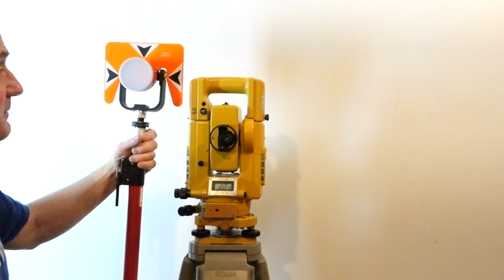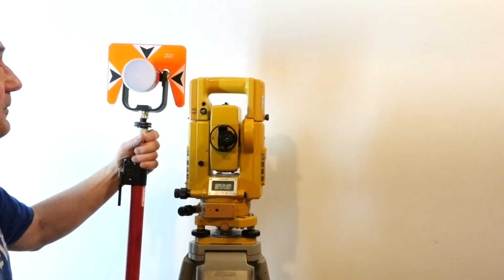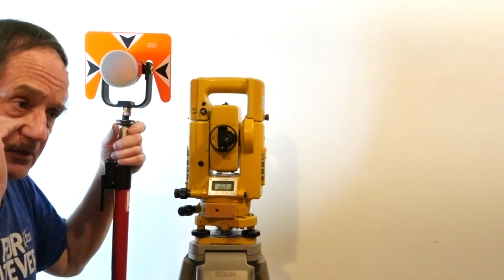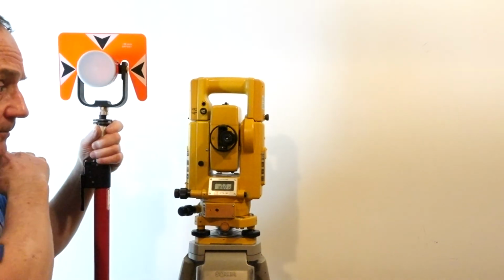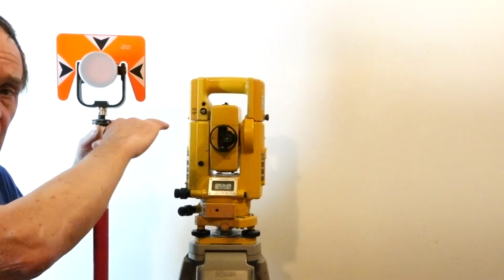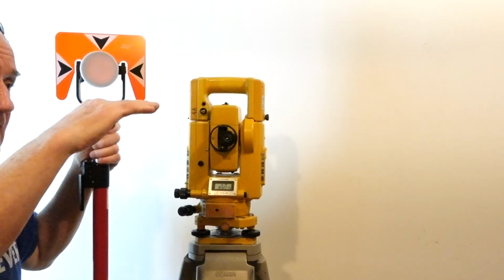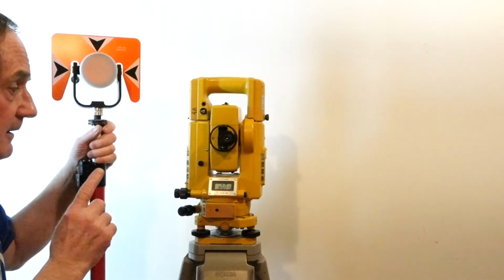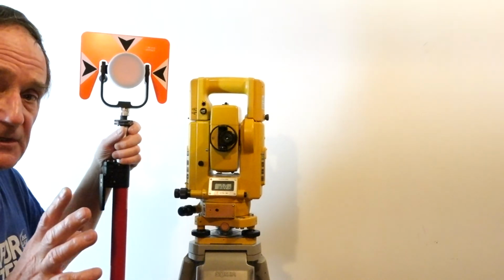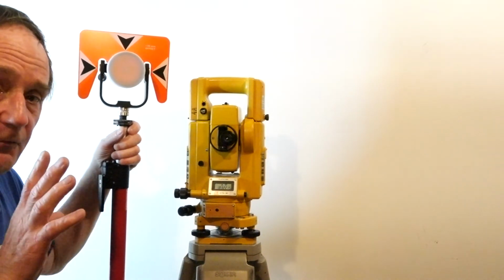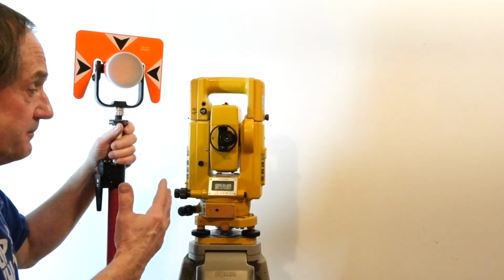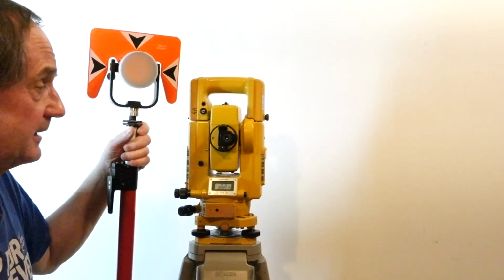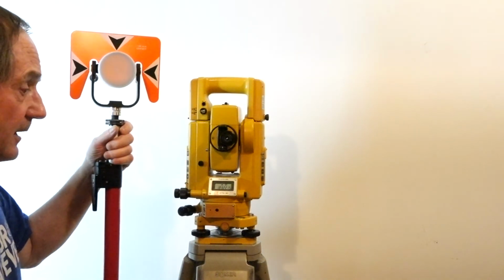So these are the basic pieces of equipment that we'll be using, but the primary one is the auto level, because what we need is a precise tangent at the point of observation. We need to establish a very, very precise tangent from which to work, and that is the sole purpose of life for the auto level. The total station can perform that, but not to the same kind of accuracy that you can get with an auto level.